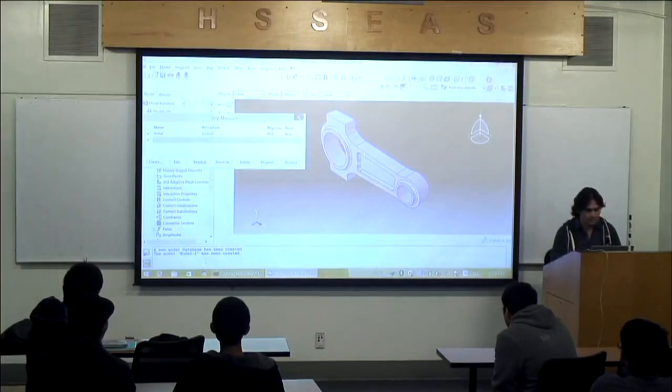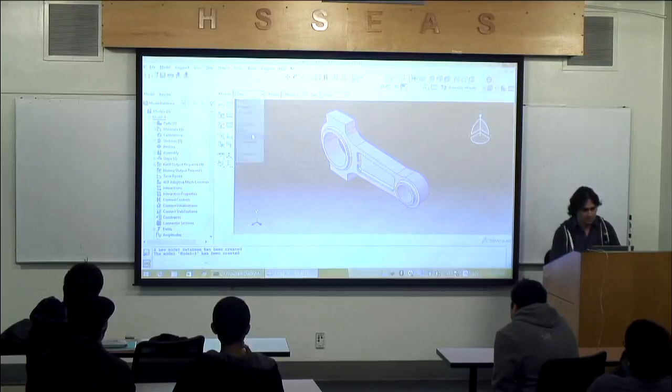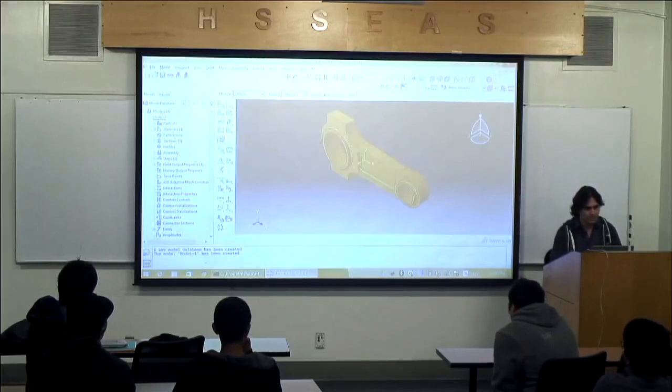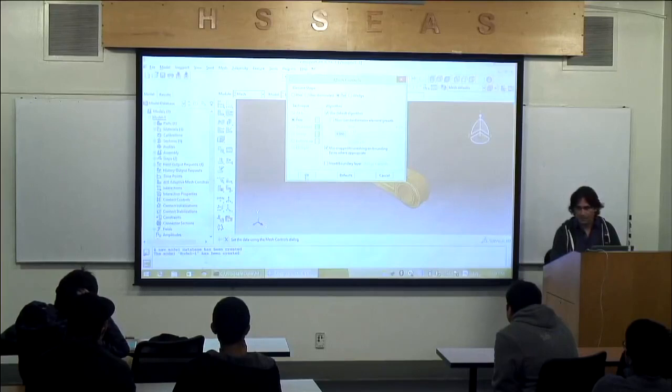And once it's done, just get back to the menu, to the module. So we don't have to do anything in the module section. So go to the mesh. In this case, we're going to select a tetrahedron element shape. The technique to mesh is going to be free.